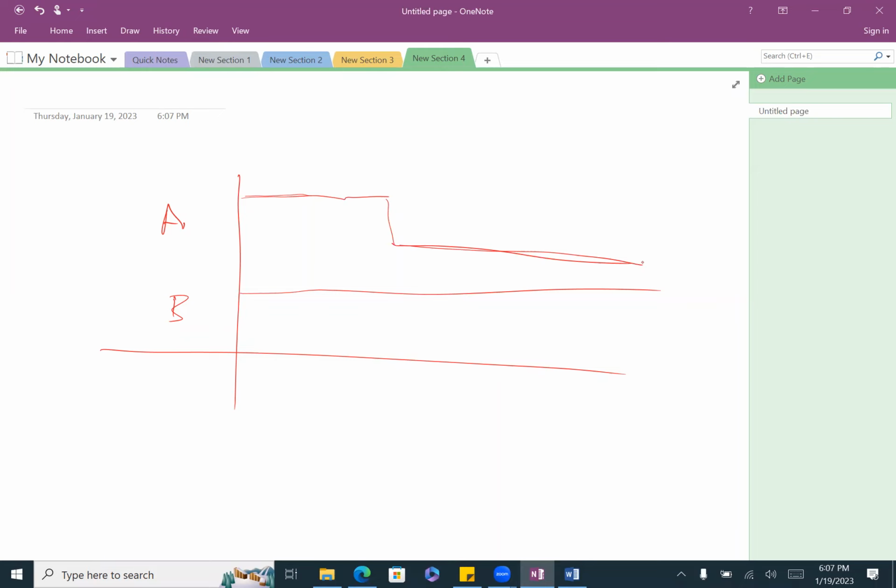So now, what will the result be? You will have the sum, and you will have the carry, correct? And let's say initially the carry from the previous stage is 0, all right? So let's work here. Let's say now you have 1 here, right? 1 plus 1, it's going to be 0, 1, correct? The result? So the sum is going to be 0, okay? And the carry will be 1.